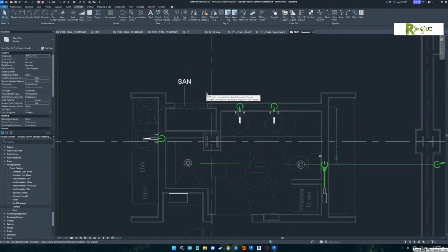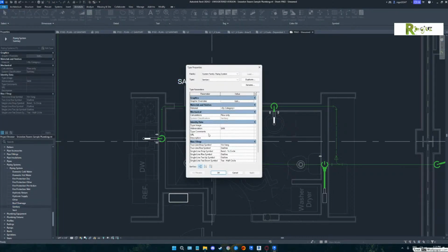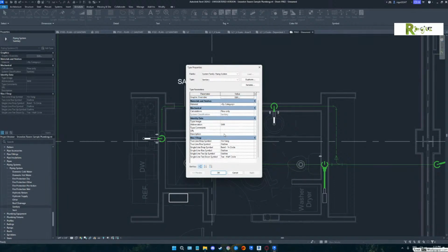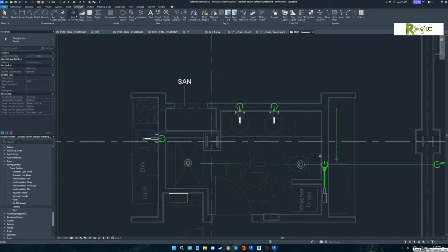See, what you would also generally want to put into that tag information is an elevation, whether you're going to go systematically by center of pipe, bottom of pipe, or top of pipe. Not for sanitary, but yes for that. Oh yeah, because sanitary is sloping. Yep. Now, sanitary sloping is what he said. So the other thing that would need to happen on this is we need to put a slope on it. Not in there. Do you remember how to do your slope tag, your spot slope tag? Yeah.